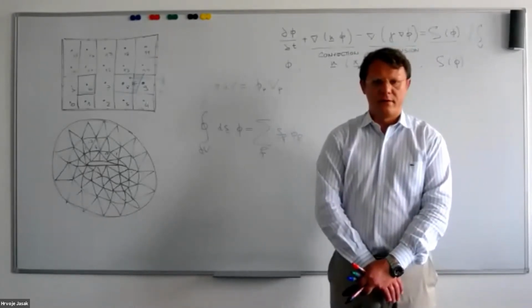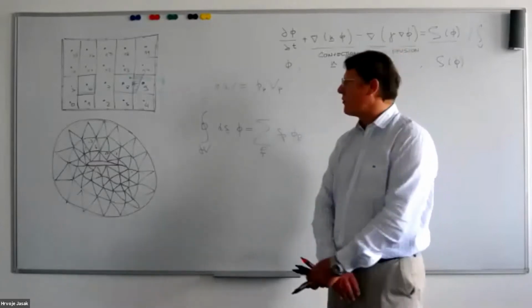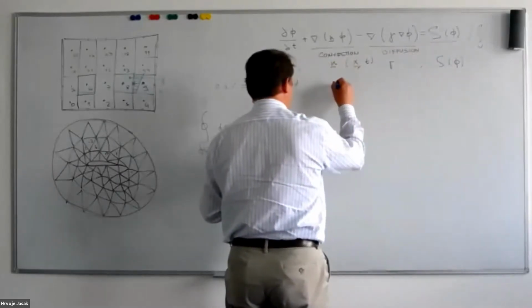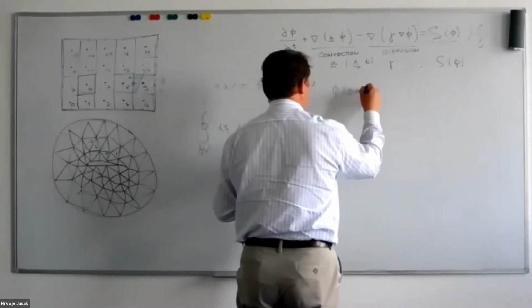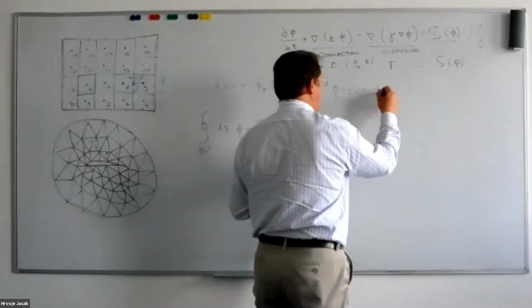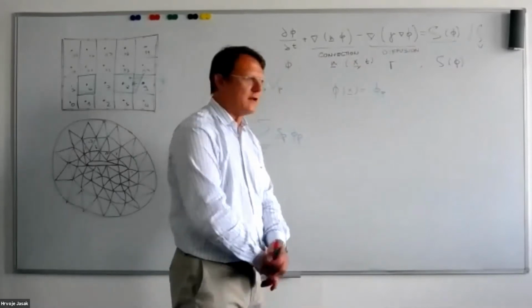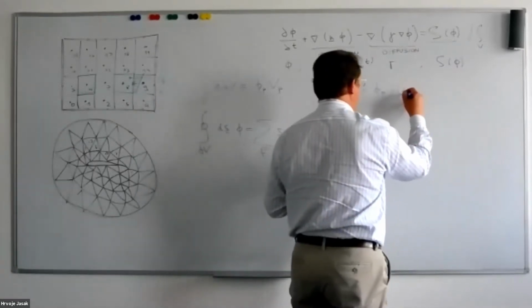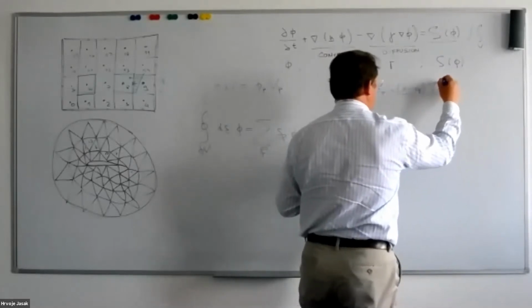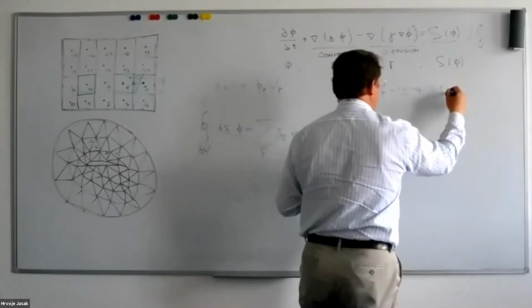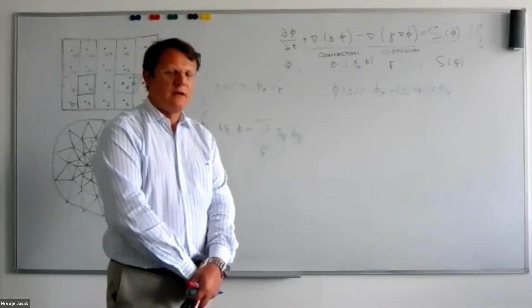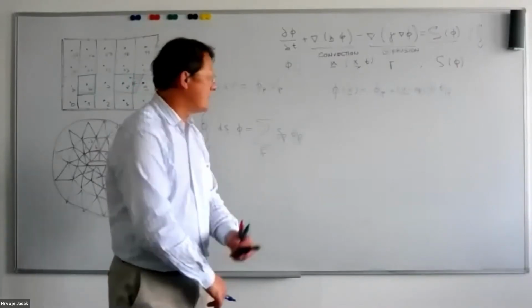In order to move the development further, let us now consider the evaluation of gradient. If you remember, I said that phi of x at an arbitrary location can be determined by finding out which cell the value falls in, and then performing linear interpolation between the cell center and the cell by multiplying it by the gradient of the cell P. How do we evaluate the gradient?